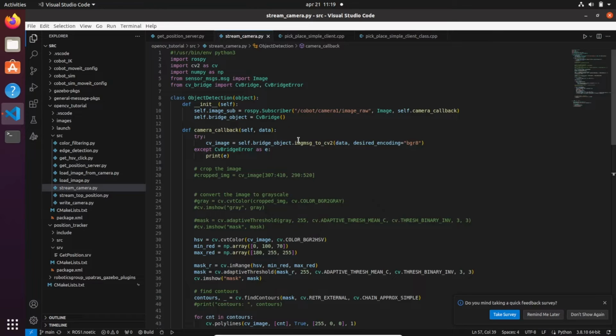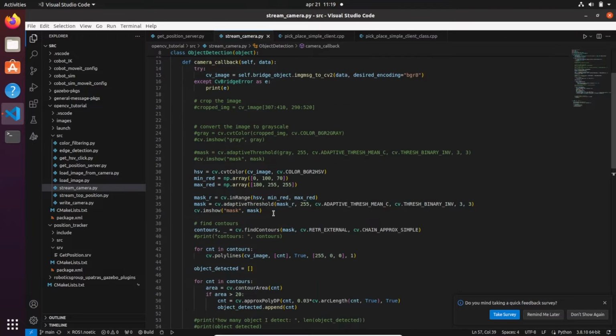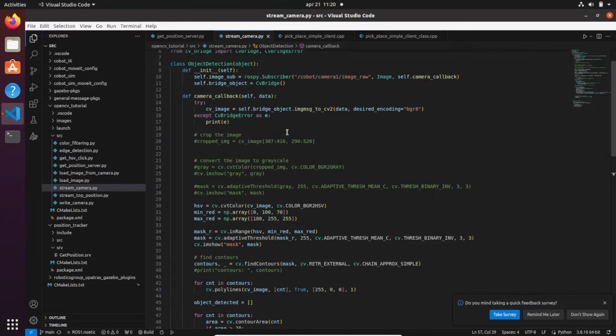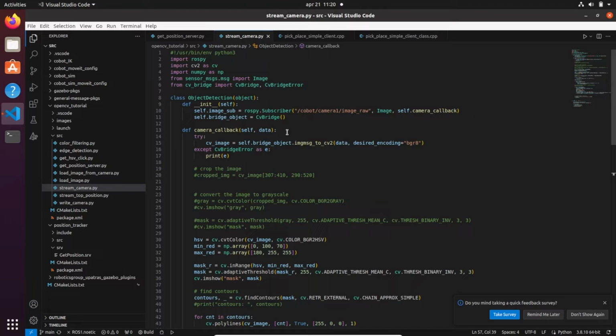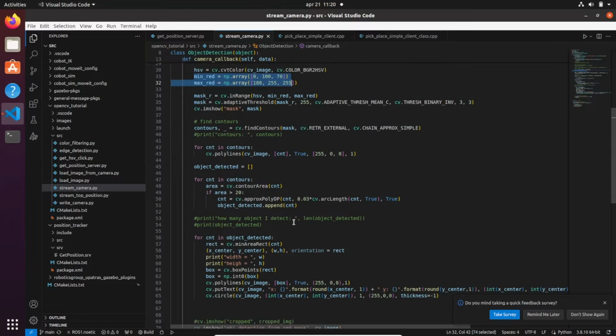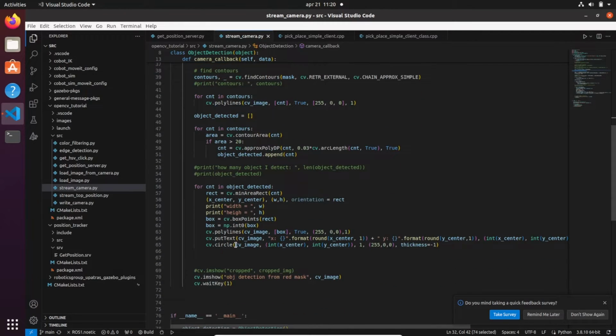Okay, here's the situation. I have already run this code with a depth camera, so I need to run this code again because now we are using a different kind of camera, a 2D camera. We will need to know if this mask based on color is correct, and we need to get the center of the square of the object in the OpenCV image that is being generated.